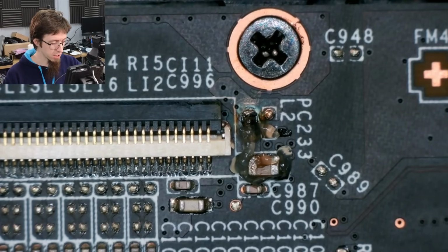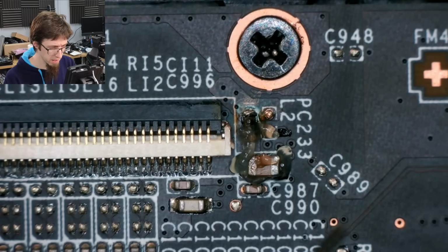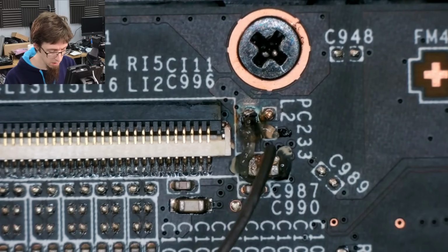And I'm going to be using a dual-wield technique because I don't have hot tweezers, which would be really good right now. However, I'm just going to come in and we're just going to put some fresh solder on that cap. And I'm just going to flux up that area and just wet the joins just so things come off a little bit easier.